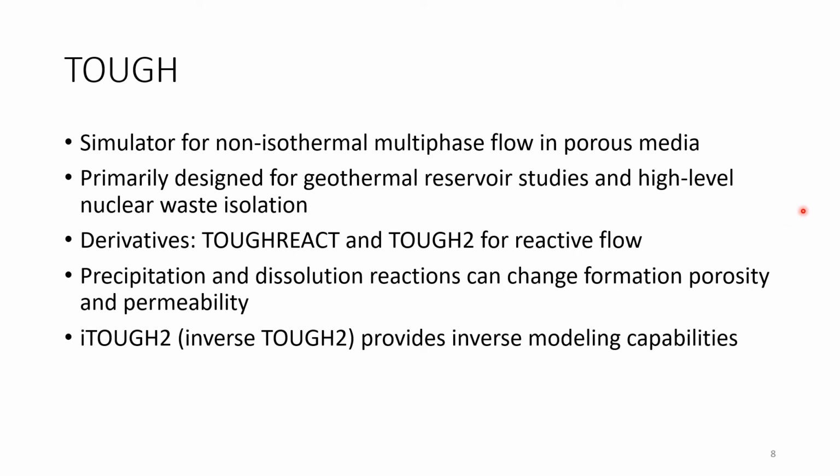If you go towards multi-phase flow, especially in combination with more chemical focus, then you will probably get familiar with TOUGH. So it's a code for really complex multi-phase scenarios, right? So going a bit away from groundwater flow here, right? So TOUGH has been developed for reservoir studies in terms of geothermal, oil and gas, or nuclear waste deposition. You can have precipitation and dissolution of minerals, which then react back to porosity and permeability. You can have reactive flow.